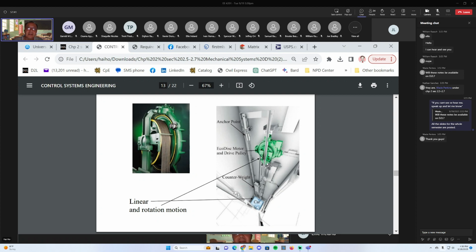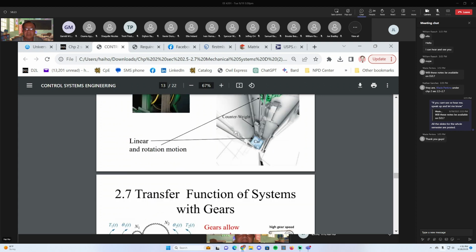So in designing an elevator system, you have to worry about picking a large enough motor that can handle the load of the car and drive the cabin up to the max speed that you want, to some max acceleration. If you want to go from the first floor to the third floor in half a second, you need a bigger motor compared to the case where you spec it to allow 3 seconds to go from the first to the third floor. Then you can have a smaller motor because you don't need as much acceleration. So that's one real example of a rotational system.